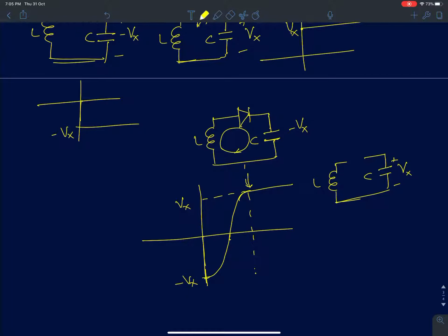Normally, if we charge the inductor using a switch in this fashion, I have set an initial current in the inductor, and for a long time the switch is closed. At t equal to 0, the switch is suddenly opened. The inductor has to lose all this energy suddenly, so we know it will develop an impulse of voltage across it, an EMF impulse, and it will lose all the current instantly. That is, if it has no other path, if it's completely open circuit.